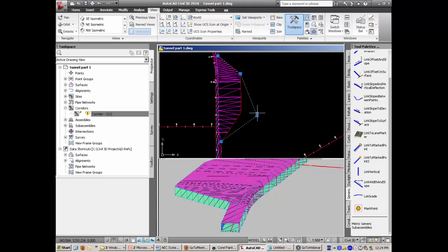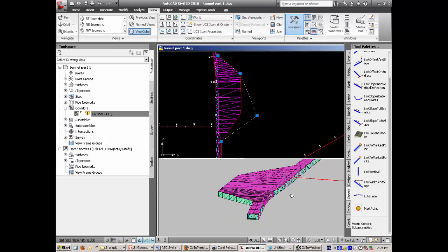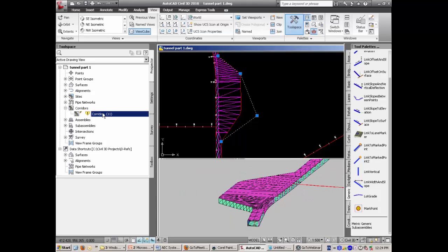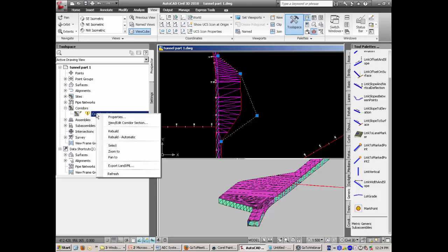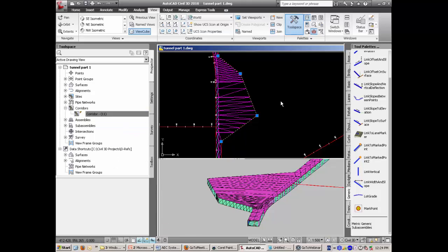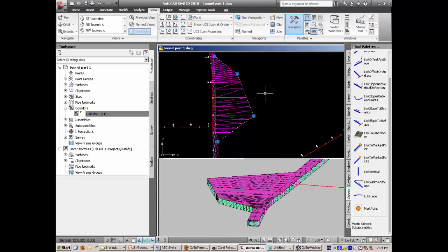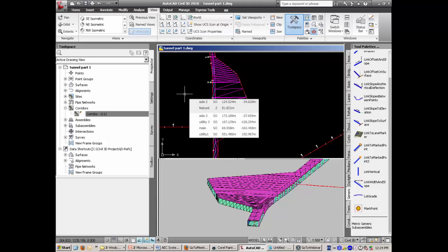And it's quite flexible. If I go back to my first one here and drag my polyline out, I'll just zoom back out here a small bit so we see what happens. So I've got my exclamation mark showing up on my corridor in the prospector, telling me something has changed. I right click that and press rebuild, and that widens out for me. So even as a simple exercise in itself, that's got great potential before we go into the intersections at all.